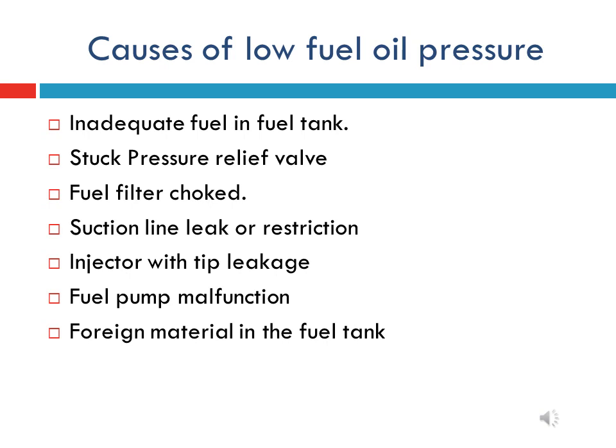Fifth is injector with tip leakage. If the mechanical unit injector is leaking, this may also be the reason for low fuel oil pressure. Sixth is fuel pump malfunctioning. If for any reason the fuel booster pump is not working properly, then it may also be a reason for low fuel oil pressure.